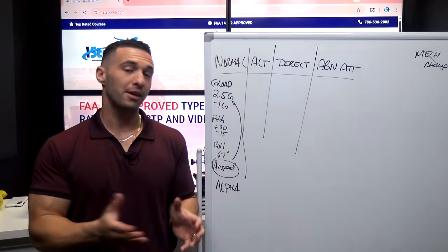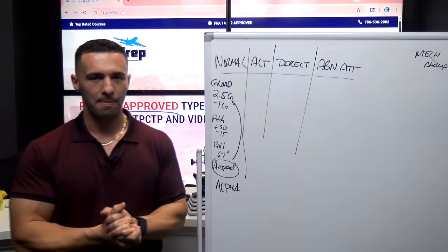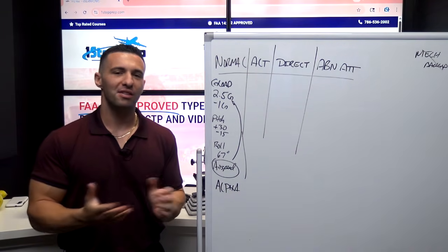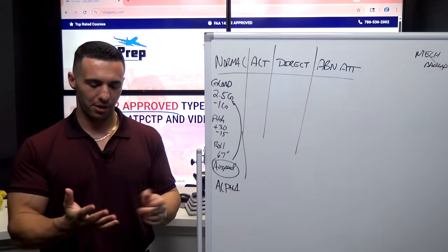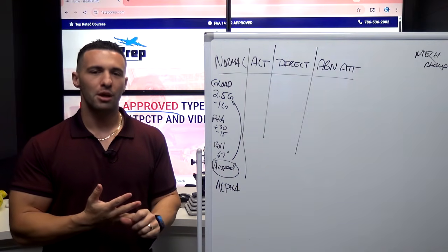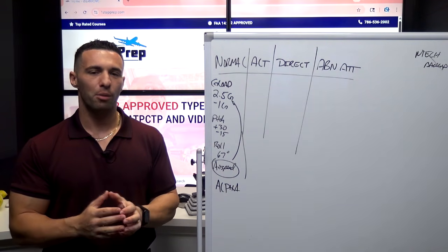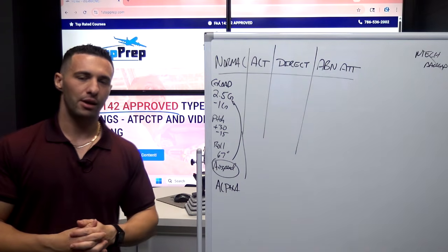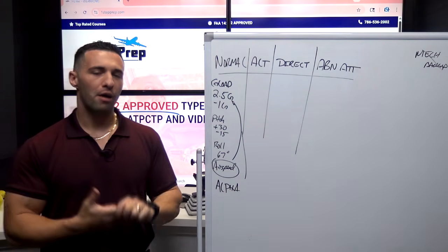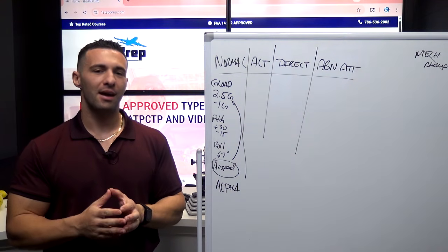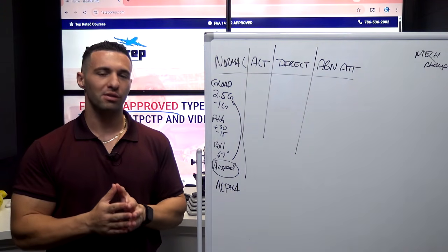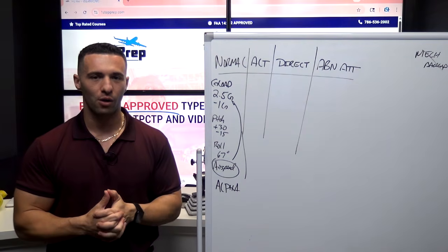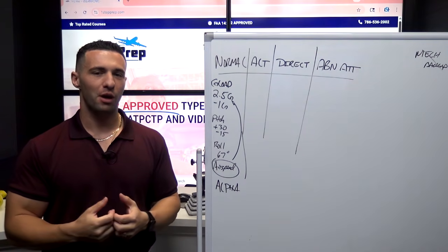So alpha prot effectively means angle of attack protection. This is Airbus's initiative to not necessarily put in a stick shaker or a pusher, but certainly install some remedy to help us not get dangerously close to stalling an aircraft. And so with that being said, alpha prot is the angle of attack where the flight control computers will intervene to prevent a stall. There's several ways of describing it.